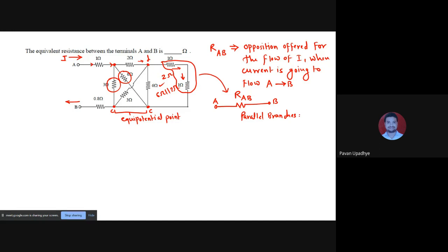Now whether this 3 ohm is in parallel to 6, yes, because starting terminal of 3 and 6 is D and finishing terminals are also same, that is C. So this is how you firstly have to conclude which elements will come in series to each other and which elements will come into parallel to each other.